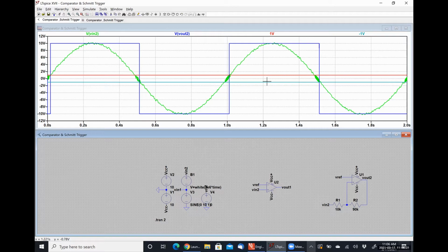Those upper trigger limit and lower trigger limits are simply a function of this resistor network right here applied in our positive feedback loop. So we're going to take a few minutes to mathematically go through and figure out what's going on and develop some expressions to figure out how we can design circuits for specific upper and lower trigger limits.